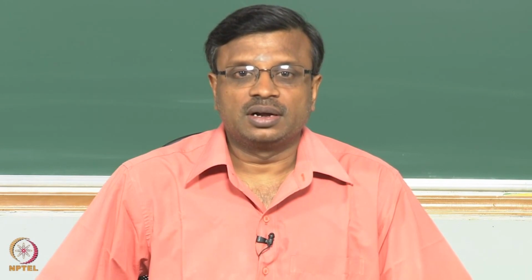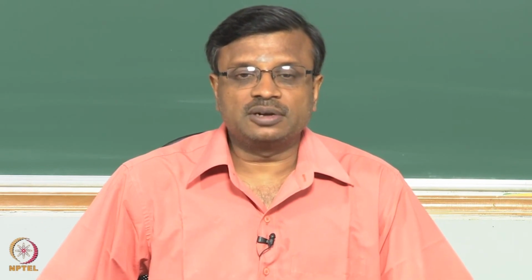So, in this class we did an important topic: flow description, consideration of the mass equation, consideration of the momentum equation in detail in differential form, writing the momentum equation in vector form and scalar form, the importance of the nonlinear convection term and why one should focus on convection term discretization, and how to represent different external forces for different problems.